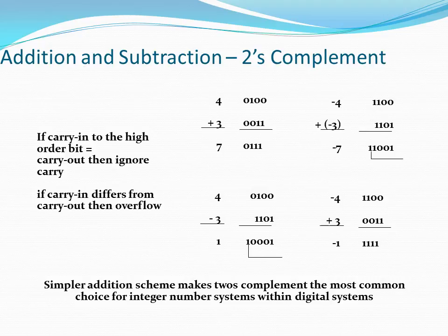But while performing addition, an overflow may occur. How can we detect overflow? For unsigned numbers, whenever we get a carry out, it is an overflow. But in this case it is not exactly so that a carry out means overflow, and we have an approach to detect the overflow. Here we have two carries, carry in and carry out. The carry present at the MSB position is called carry in, and the carry going out of the MSB bit is called carry out. Whenever the two carries are not equal, we can say that overflow occurs.